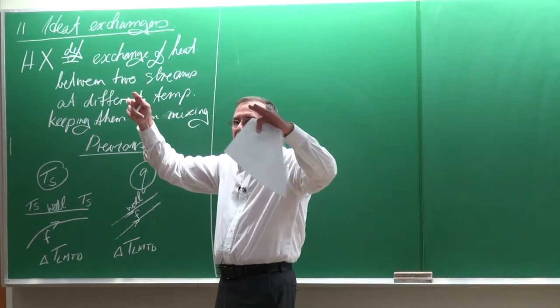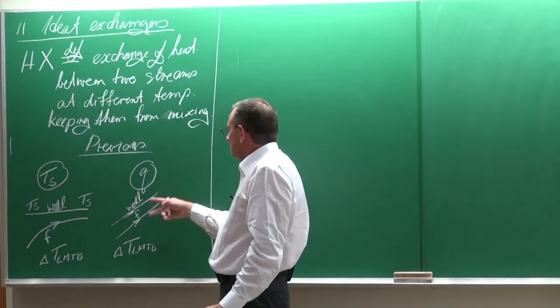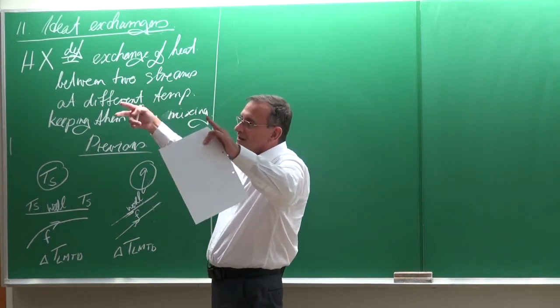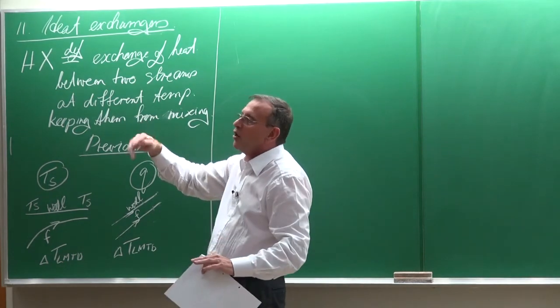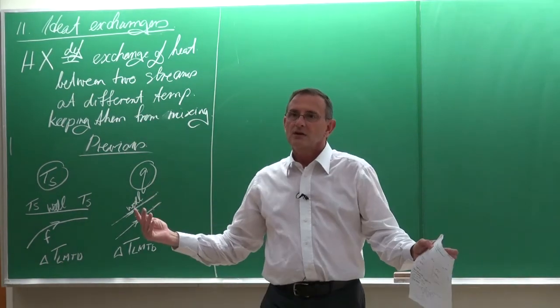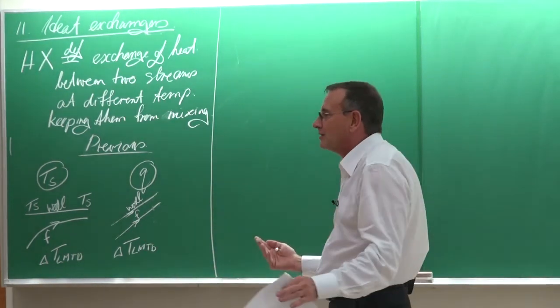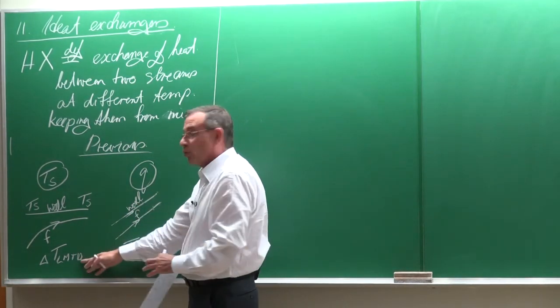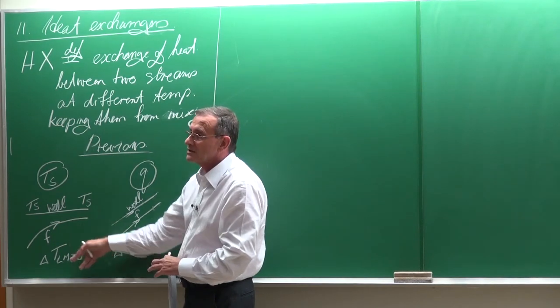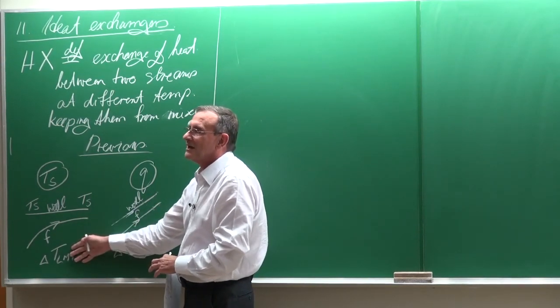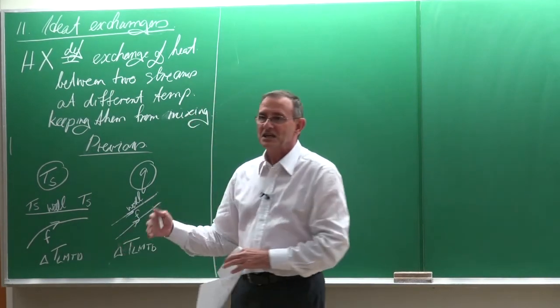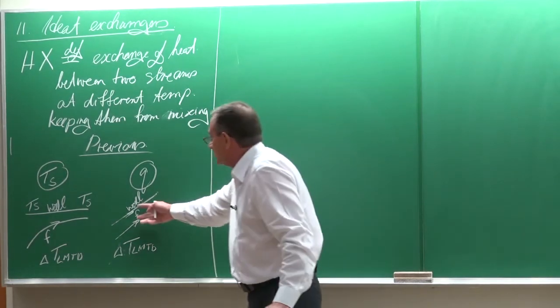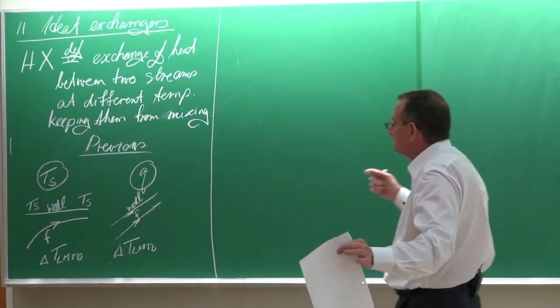So with LMTD, you're going to get this temperature difference minus that one is 0, divided by the ln of 0 divided by 0. So you will immediately see it can't work. So what I would recommend is always try the LMTD in any case, in previous cases. And if you get to this, you're going to see it doesn't work. And then you use just the temperature difference.